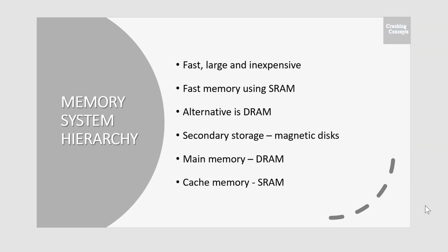Let's begin. An ideal memory would be fast, large, and inexpensive. A very fast memory can be implemented if static RAM chips are used. But these chips are expensive because the basic cells have 6 transistors, which preclude packing a very large number of cells onto a single chip.